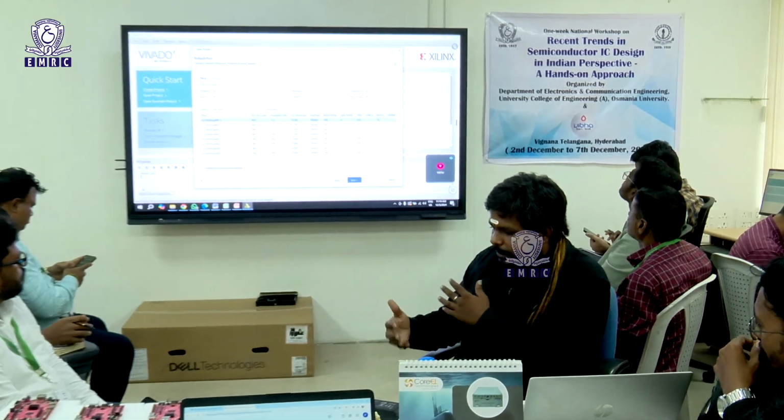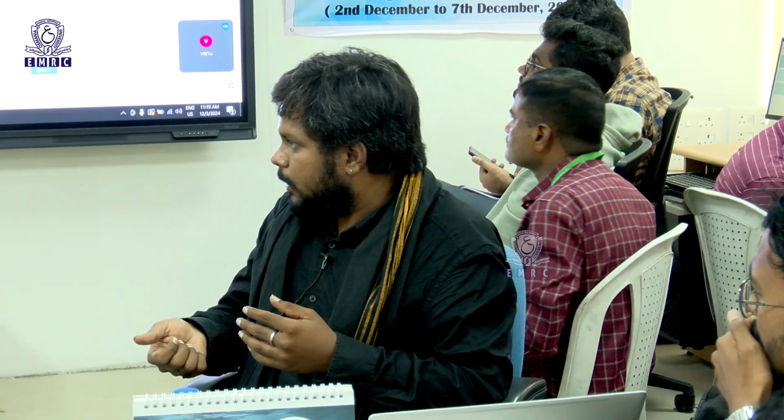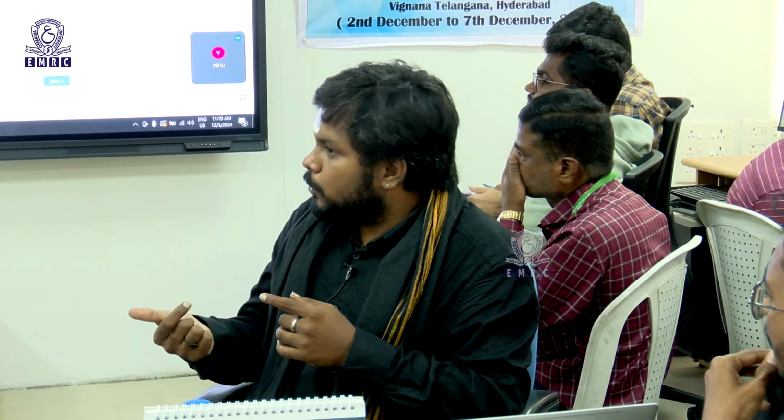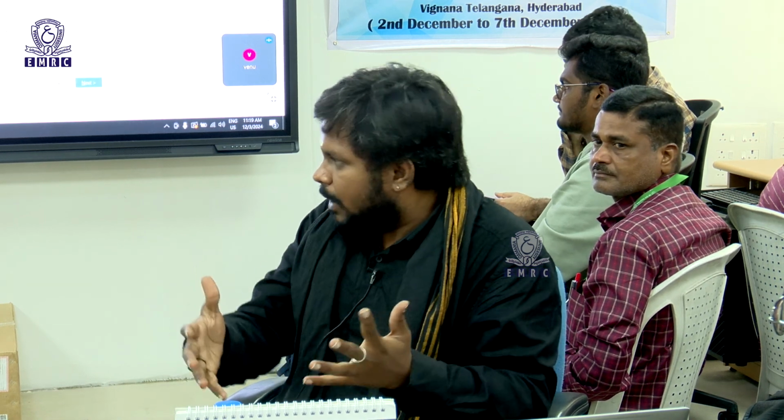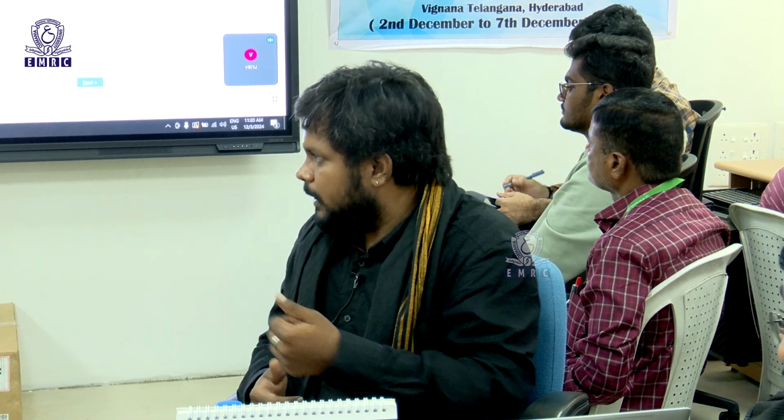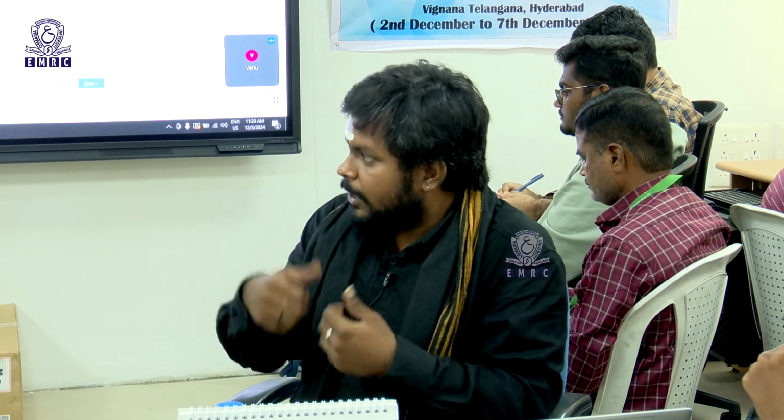This is completely project oriented, but you can see what packaging you require. Do you need thermal shielding? Do you need radiation shielding? If you are working on a design that requires a chip that you are sending to space, then you need thermal shielding, radiation shielding and multiple other things. If you are sending it on a submarine, or directly dumping it into the ocean to track the ocean waves, then you need waterproofing. So all those kinds of things are required.